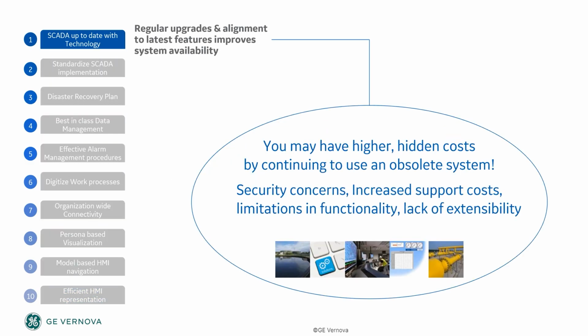So the first one, I believe, is a no-brainer. I mean, this is something that I would expect a very large part of the audience today has already checked off. The key aspect of this is ensuring your SCADA is cyber ready or is easily supportable. We have often had water customers lapse in upgrades that makes their supportability challenging. So before you think of any advanced analytics, simulations, mobile or web interfaces that you may want to add, please make sure that your SCADA is up to date with versions, OS patches, and other security updates. This will enable you to start with the right platform to expand.